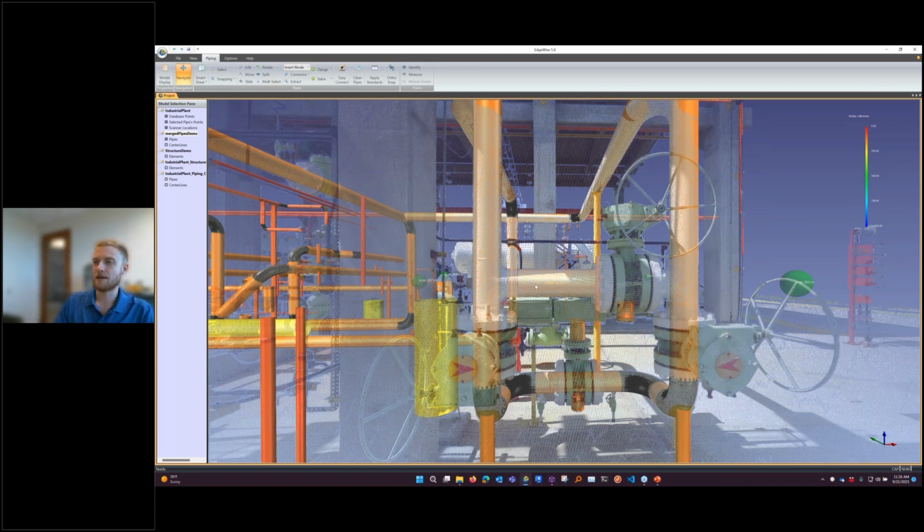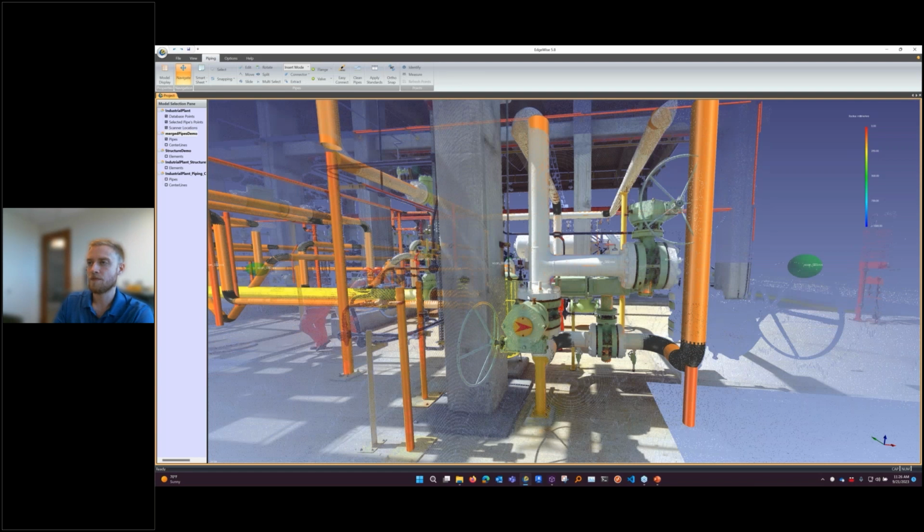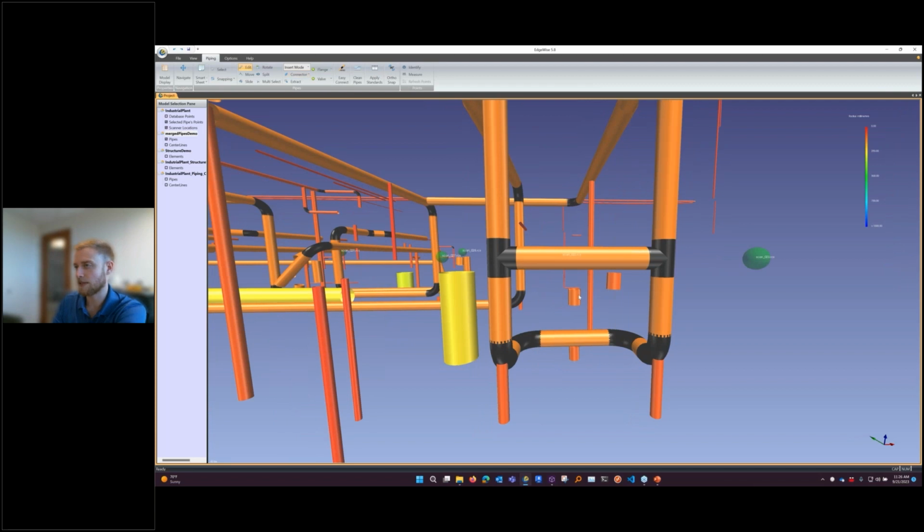In this case, I have this nice little meshing view here that makes it easier to see things, but I can model from this view as well. And to add a T, it's as simple as just grabbing the end of the thing I want to connect and grabbing the other end. So it's really easy for me to drop in stuff to actually create things. I can get rid of stuff if I want to get rid of things.